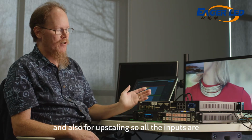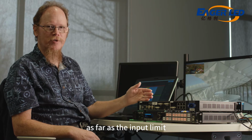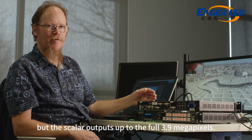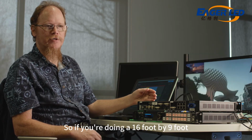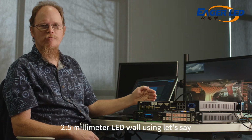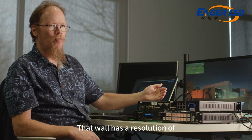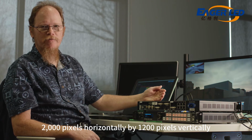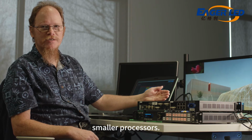So all the inputs are HD 1920 by 1080, 2.3 million pixel as far as the input limit, but the scaler outputs up to the full 3.9 megapixels. So if you're doing a 16-foot by 9-foot 2.5 millimeter LED wall using, let's say, the Epson Polaris 2.5 Pro, that wall has a resolution of 2000 pixels horizontally by 1200 pixels vertically. It exceeds the capability of all of the smaller processors.